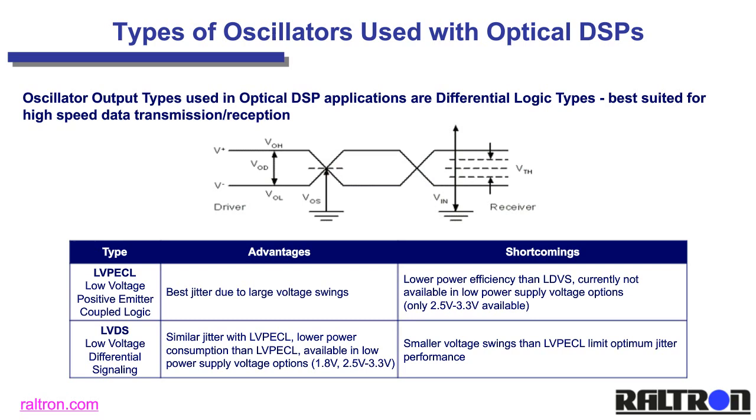Look, there is a race that has to do with bringing ICs to market, because the primary limiting element for such an oscillator is the jitter that is generated or not by the IC that is used in the oscillator. So the latest generation of ICs for LVDS are generating jitter levels that are not so far, a few percentage points away from the LV-PECL level.